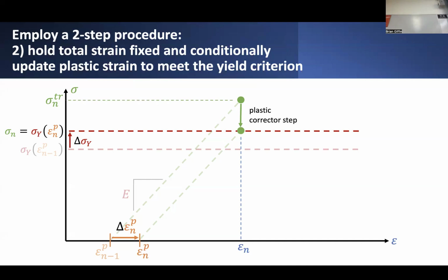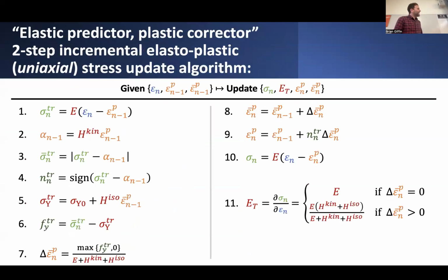And you can figure out exactly how and when they meet each other, so that you guarantee that you're going to lie directly on this updated yield surface during the plastic corrector phase. So that's the simplistic interpretation of what's going on. Ultimately, we want to lie directly on the yield surface if previously we were outside the yield surface during the elastic predictor step.